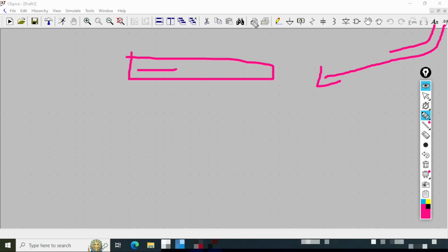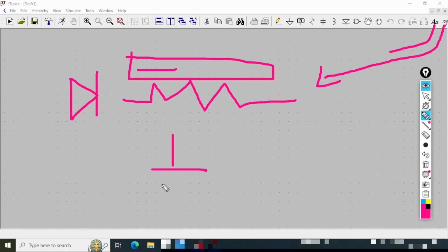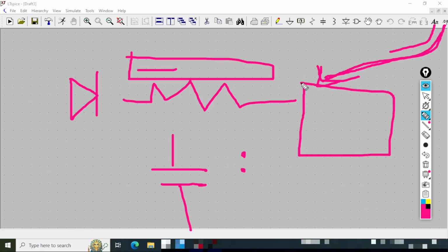The interface here will help you to draw the schematic. That means you will place the components like diodes, like resistors, like capacitors. Okay, it will help to draw. But however, for spice related commands like .inc, .measure, all those things have to be accessed through this particular command. So all those spice things you have to write by hand using this so that they get incorporated along with the schematic.